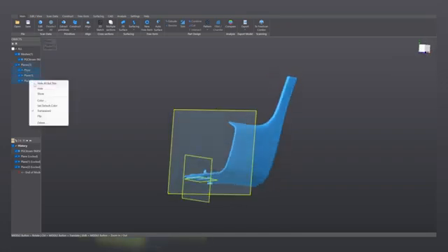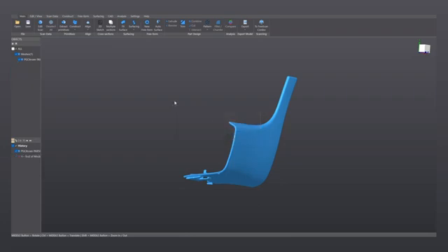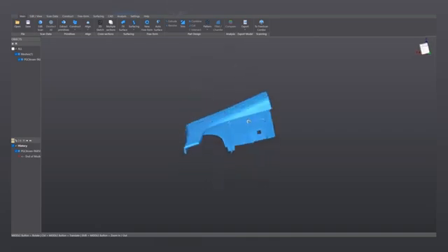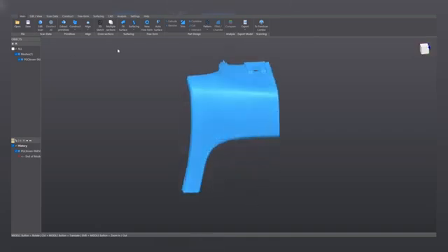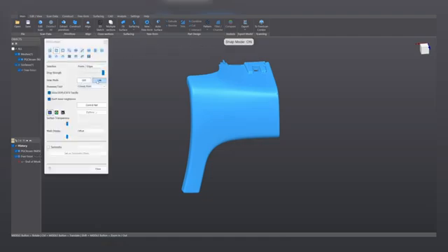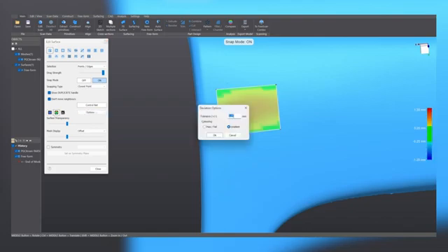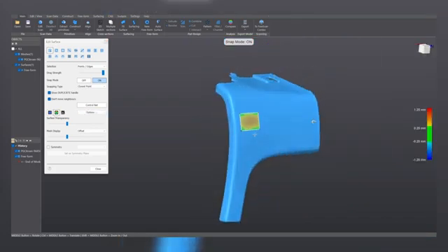Right, we can delete these planes. We don't need them anymore. And we proceed with the surfacing task. To do it, we are going to create a new freeform, and we are going to make sure that the snap mode is on. We start drawing one small face over here. And personally, I prefer to work with the tolerance options on, in this case with a value of 0.25 millimeters.